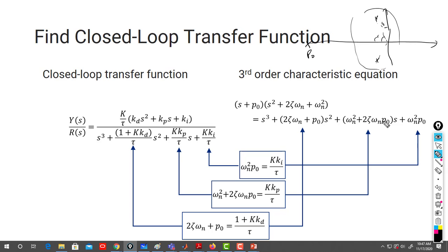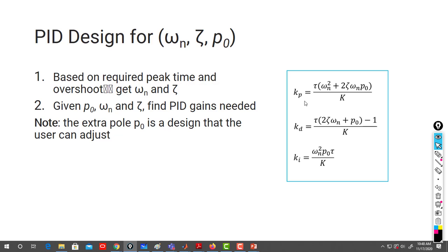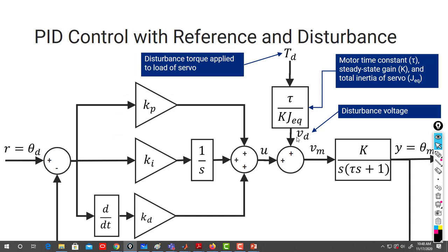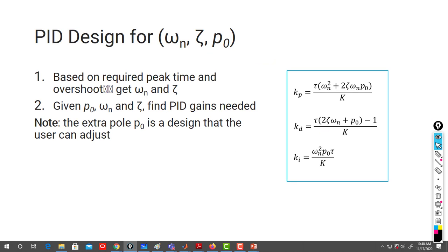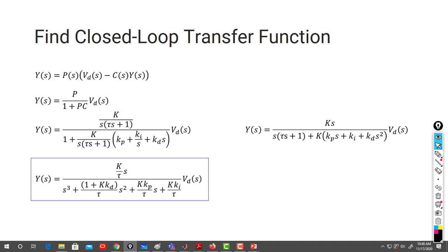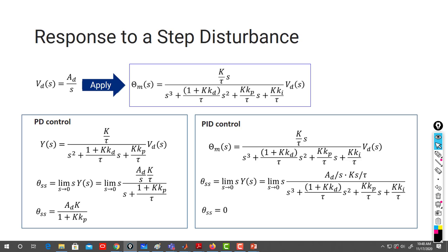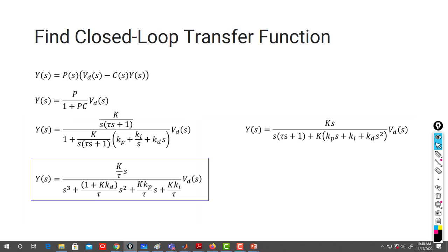If a first order system, take two poles far, so you can neglect them, and then your response will be equivalent to a first order response. You do the calculation, you get Kp, Ki and Kd. Alright, and that's it. I recommend you go over the remaining few slides. Nothing new, because you basically know them.